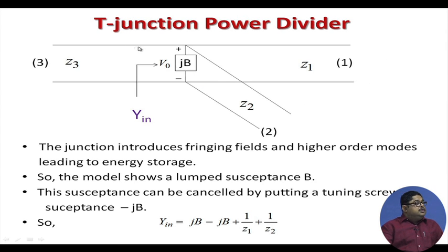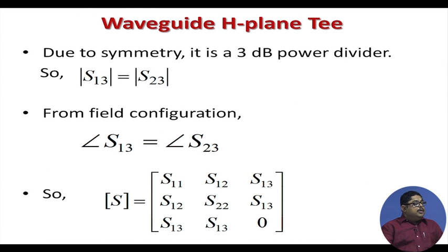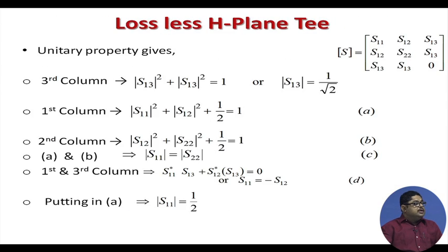Now, the T junction power divider that we have done earlier, you see deliberately by our design we have taken the two ports as the same structure. By this we have made the impedance values of this waveguide line and this waveguide line the same. That is why we got equal power division, but always we do not want equal power division. Sometimes I may need 40% power to go to one arm, another 60% to go to another arm. So what I do, I will have to play with the impedances, that will show now, that unequal power divider.